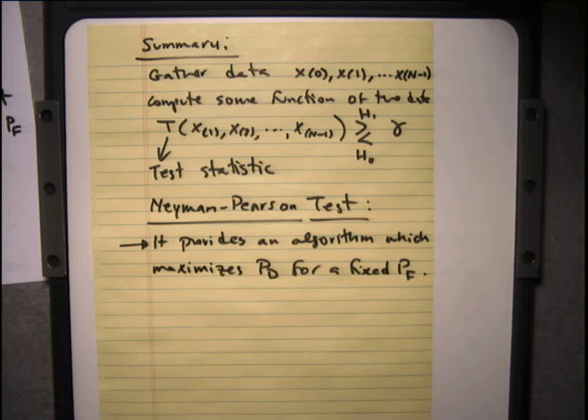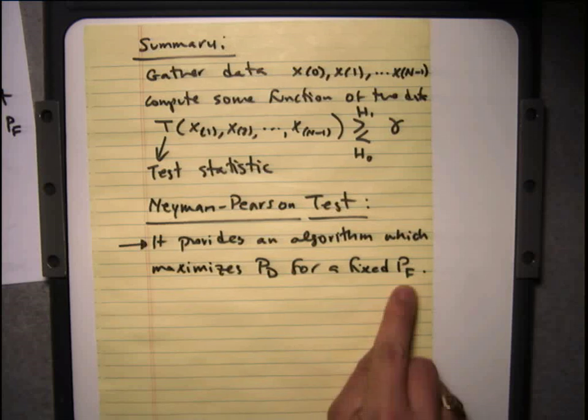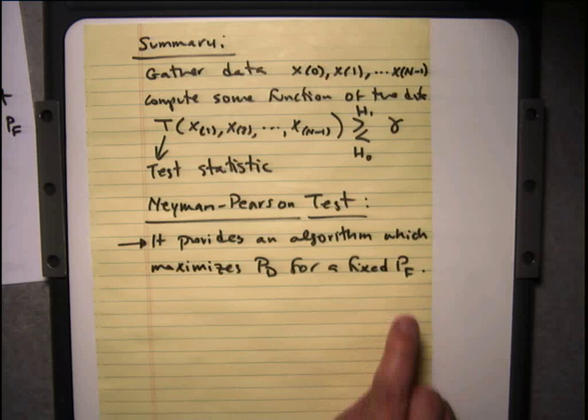When should they go off? Somebody makes a decision. Somebody says, I want my probability of false alarm to be less than once every 100 days. In other words, if there's no fire, I don't want the fire alarm to go off. Not ever, because that's not practical, but it shouldn't go off more than maybe 3 times a year for no reason. Okay? So that's once every 100 days or so.